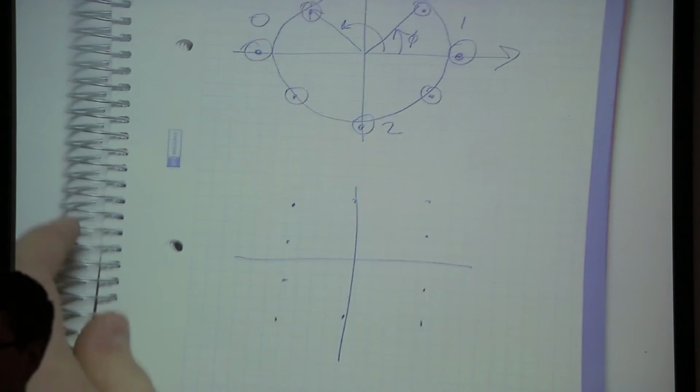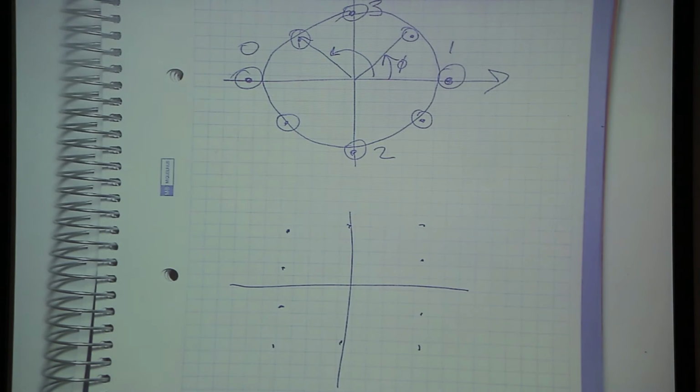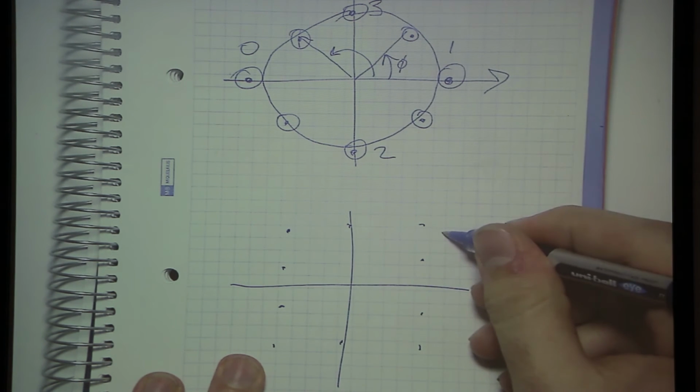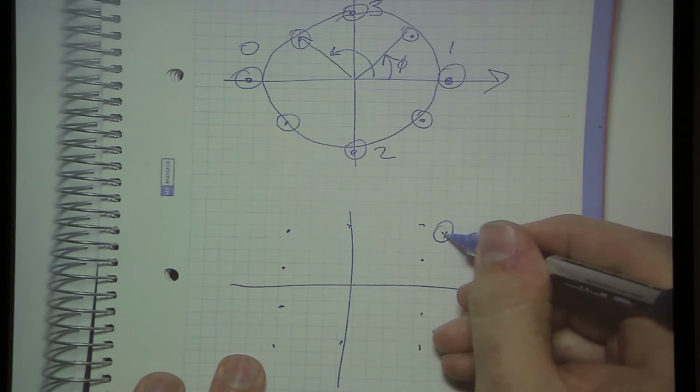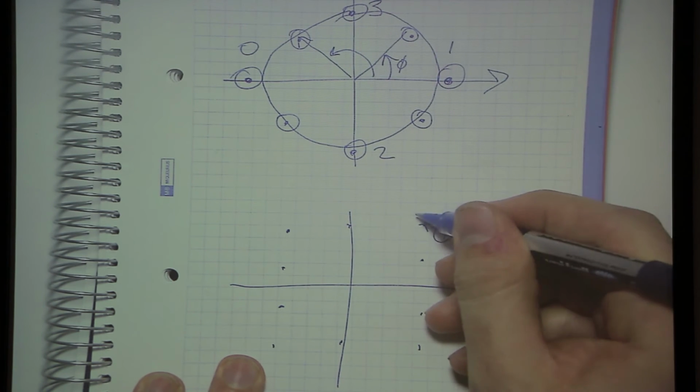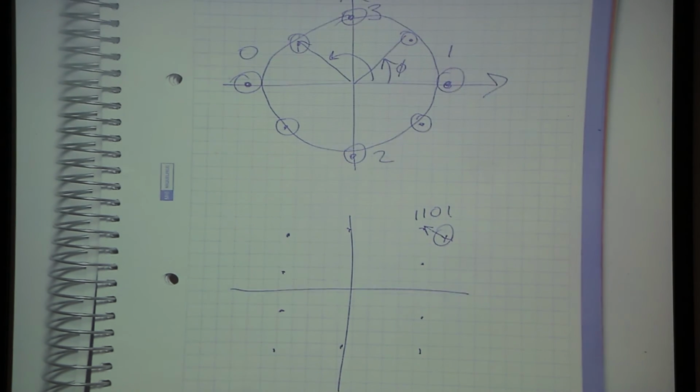And then you pick one of these points and you transmit it. And this, as you can probably imagine, is really easy to decode if you have this IQ data. You receive some point, and it's like here. And you say, well, it's closest to this point, so it was probably the value 1101. And then you keep repeating that, and that's your data stream.